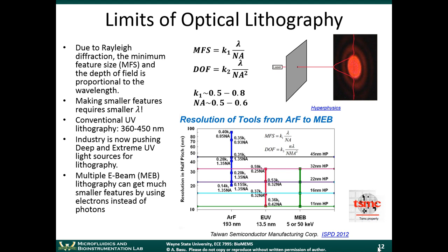When we're talking about lithography, this is sort of a segue into this. We're often interested in the minimum feature size. Okay, I think I had shown you in the first module a chart of Moore's law, right? I said that the transistors are getting smaller and smaller as we go in time. Now, the reason why in the electronics industry they were miniaturizing is that by packing more transistors on a chip, you could get more complex functionality that the processor could do, more calculations, and also, as it turned out, the speed of the transistor improved when you made the transistor smaller. And also the power consumption per transistor decreased when you made the transistor smaller. There were a lot of benefits towards miniaturization there.